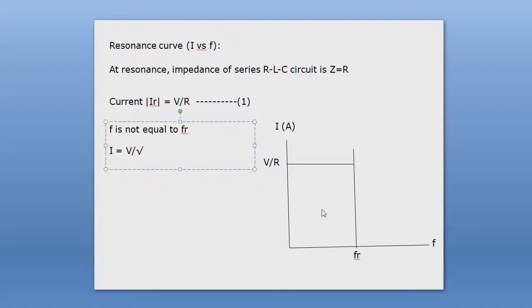The impedance of the circuit is Z equal to square root of R square plus omega L minus 1 by omega C, whole square. Is it correct? We have derived this thing so far. This is the square root of this term.